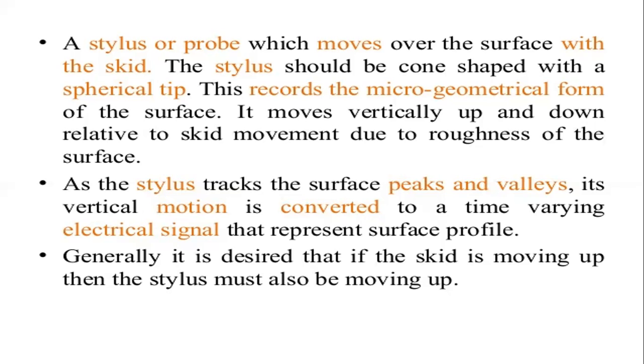Its vertical motion is converted to a time varying electrical signal that represents the surface profile. So the microgeometrical forms in the vertical direction are converted to a time varying electrical signal, that is a digital form, to represent the surface profile.